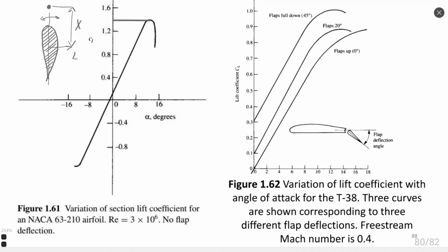it also can happen, because once the rocket is not going according to trajectory, for example, there is some side force. If the rocket is inclined, the side force also creates lift, which is contrary to the action of wind, and it stabilizes the rocket. So lift force is extremely important. I think it's even more important than the drag.